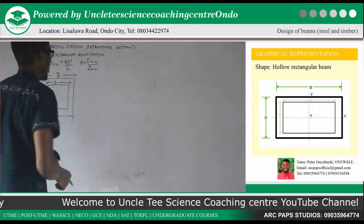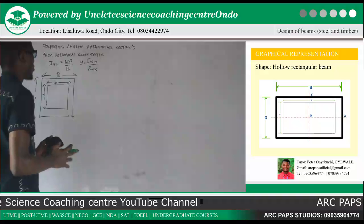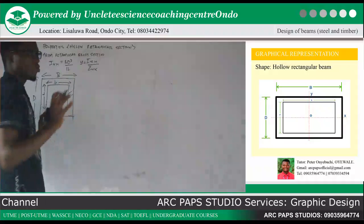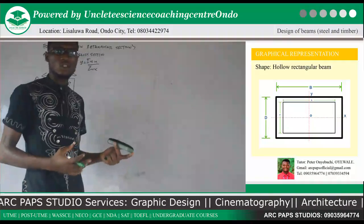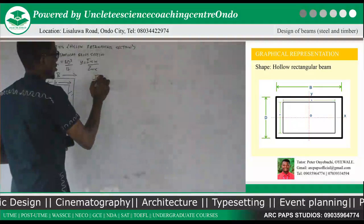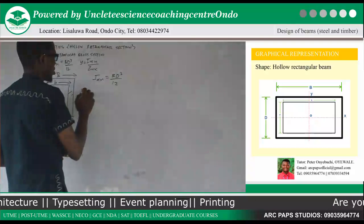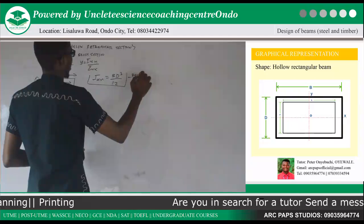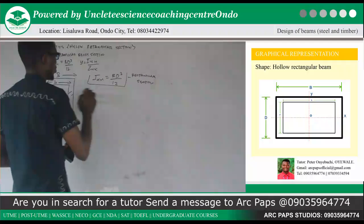Okay, welcome to this particular section, and here we're going to be dealing with a hollow rectangular beam. Now you can see I've brought out the diagram where we have our big B, our small b, our big D, and also our small d. Now you are going to see how we are going to get our moment of inertia and also our sectional modulus from this diagram. Now, since we know Ixx to be bd cube over 12, which is for a normal rectangular section.